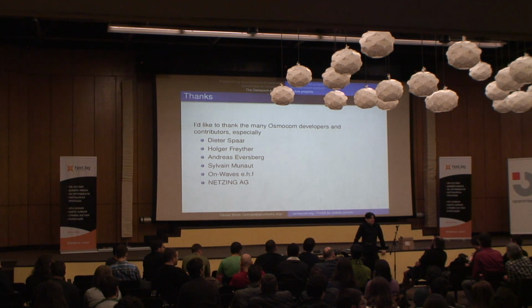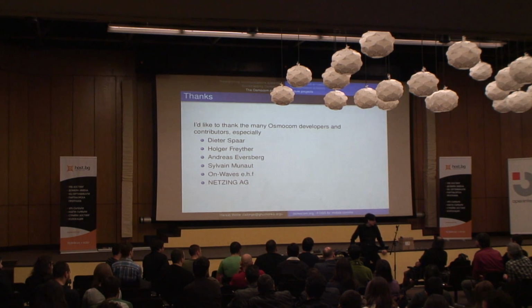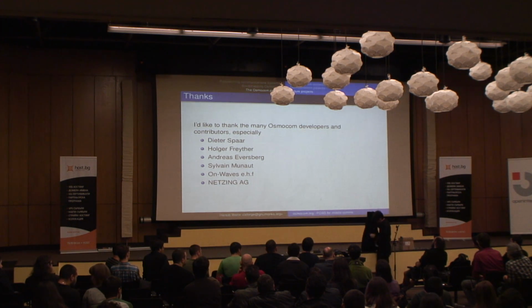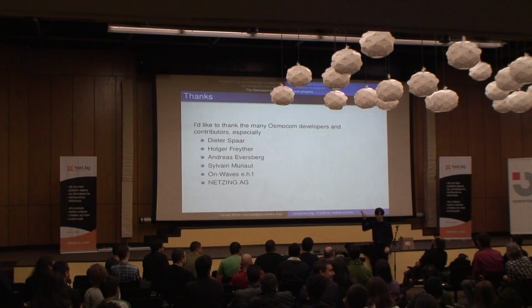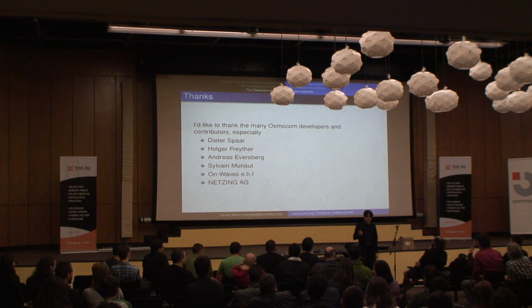Well, it always depends on what you want to look at. But if you want to play with something that generally is a phone, and you want to try to send some strange messages to an operator or something like that, then definitely OsmocomBB is the software you would want to use. And in terms of hardware, I would recommend one of these Motorola C123 or C118 phones. I think I have one in my pocket somewhere. Yeah, so it looks like this. It's a really, really old, crappy, cheap phone. Costs about 20 euros, sometimes even cheaper. And that's the best supported platform from OsmocomBB.